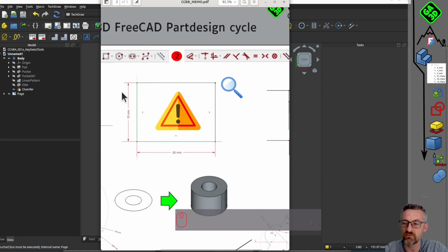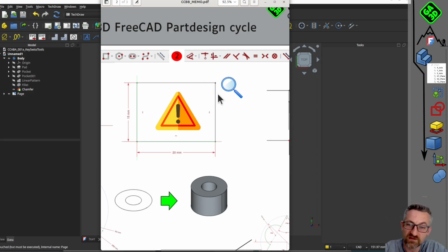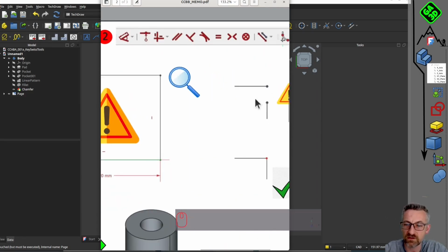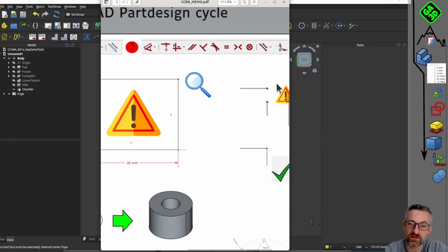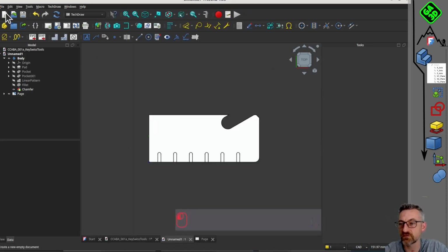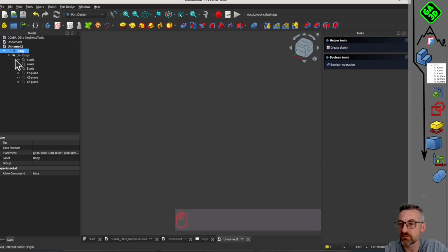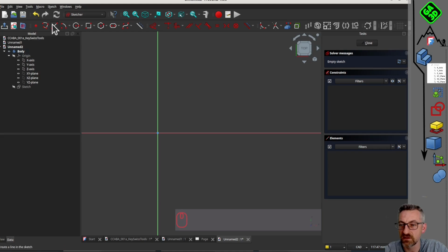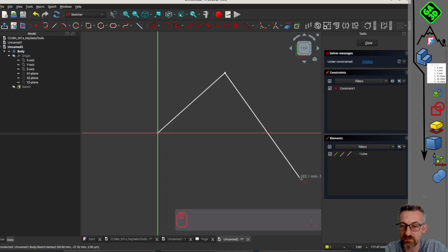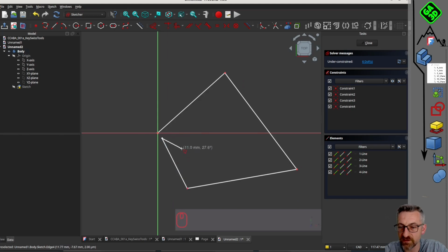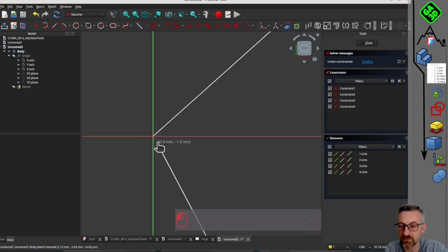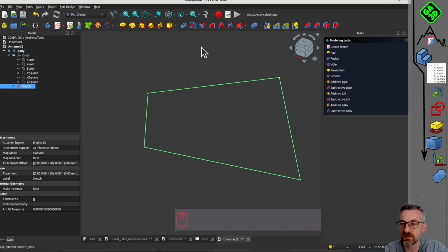Another thing to learn as a beginner is a convention in FreeCAD. Typically, this sketch here actually gives this volume. So we will create the material between the outer contour and the inner contour. And something that will very likely cause problems if you tinker a bit: you might think, oh, it looks all good. But then you notice that it's not quite green. And if you look in detail, you'll see. Because you changed something, deleted an element, or added something, and didn't properly connect your vertices. If you zoom in a bit, you'll see that it's not connected. Once it is connected, the point appears in red.